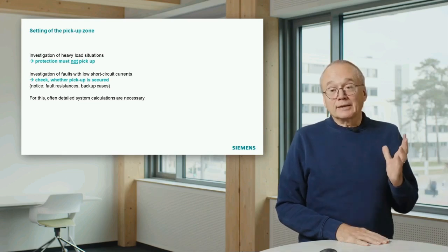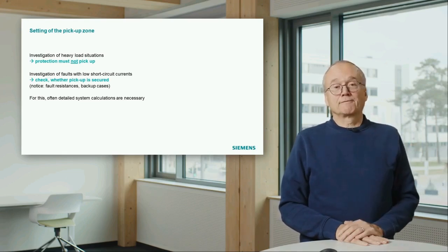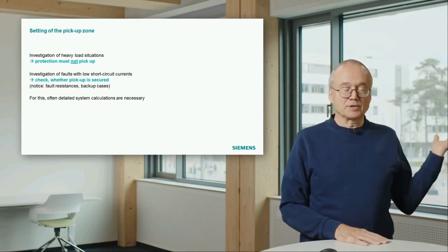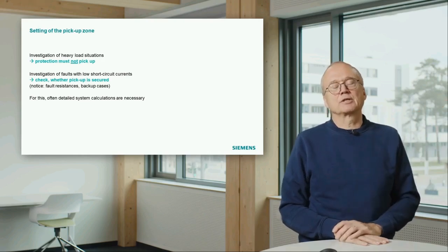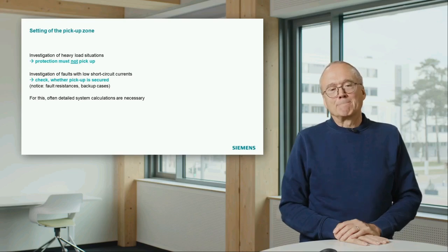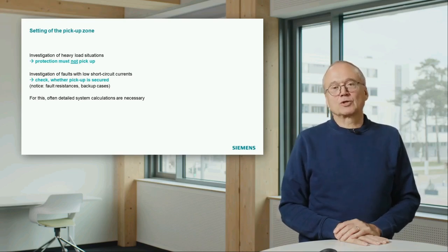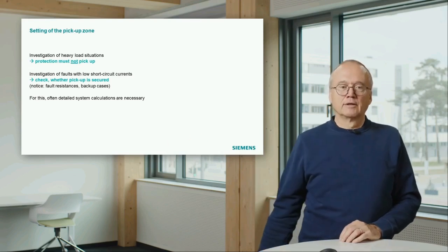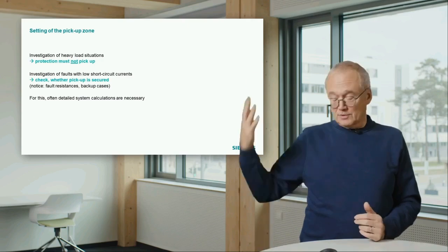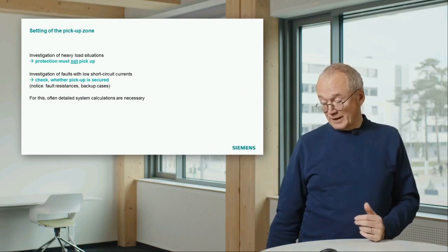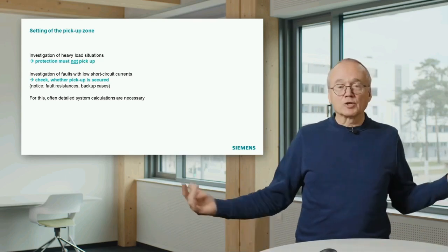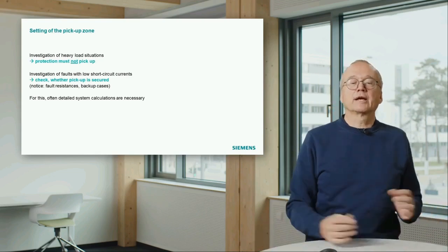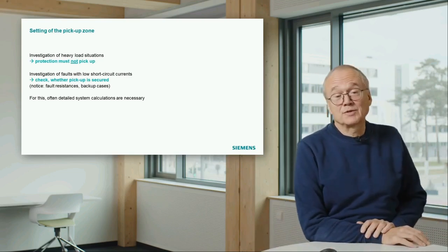But of course, theoretically, you can also have something else. In a distribution system there could be a risk that a tree falls into the line. In transmission it's not so critical. But of course you could theoretically also have a broken wire, for instance in a sub-transmission system, a wire falls down to earth, and if you have a rocky area or somewhere in the desert, you can have pretty high fault resistances there.